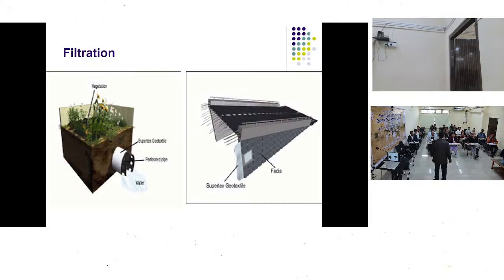Now, once this application comes to mind, the property I need to look at in my non-woven geotextile is its permeability characteristics. This means I have to define the permeability of the non-woven geotextile, and I should also know its opening size, because that opening size and that permeability will allow me to decide what type of material it will not allow to pass.